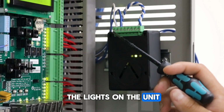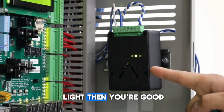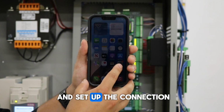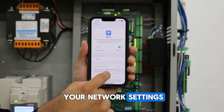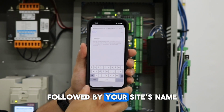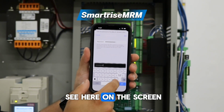Check the lights on the unit. If you see a green heartbeat light and no red fault light, then you're good to move forward. Once that's confirmed, you can go ahead and set up the connection. On your phone, open your network settings, look for a Wi-Fi option labeled C4 or Evolved followed by your site's name. When prompted, enter the password you see here on the screen.